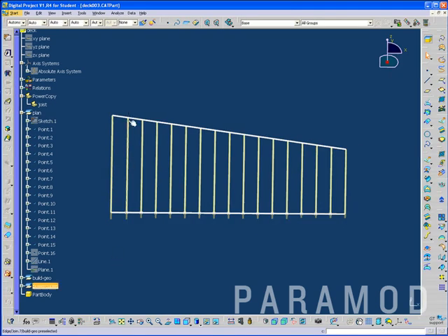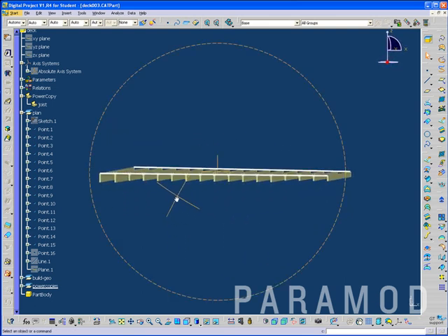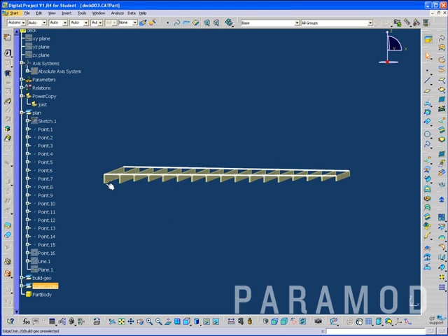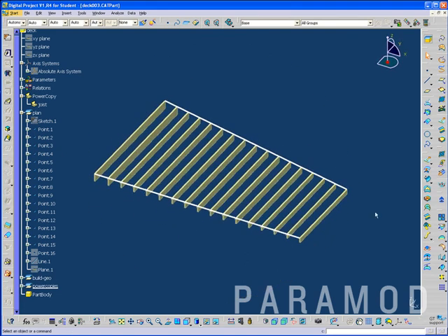we can see that each of these knows how long they are and then adjusts accordingly. And so here we can see when it meets the threshold, when it's no longer necessary to be a 2x10, it drops down. And then the same thing is true as it drops down over here. So we'll talk about how to set up that rule and then how to structure the power copy to make it so this works. So I'll close this.